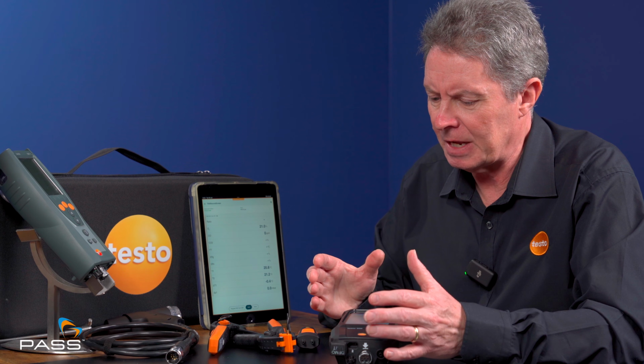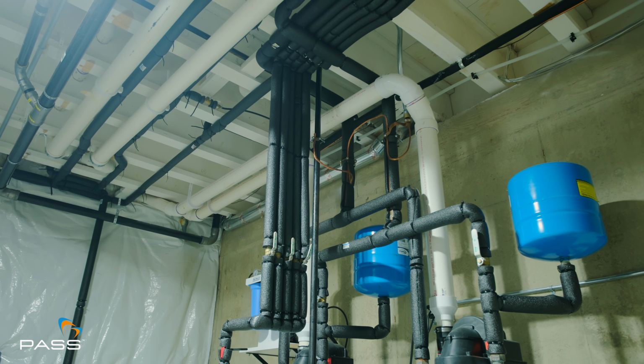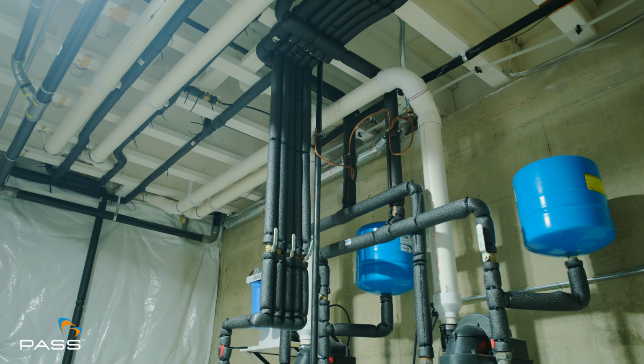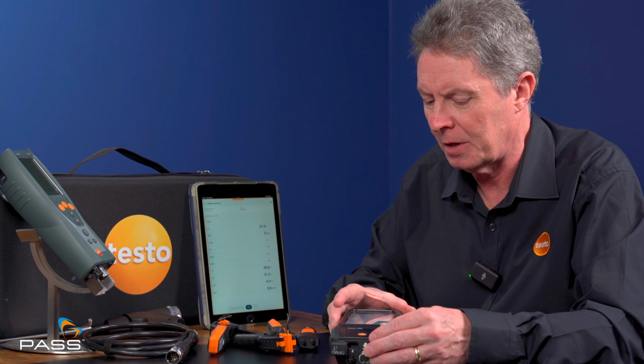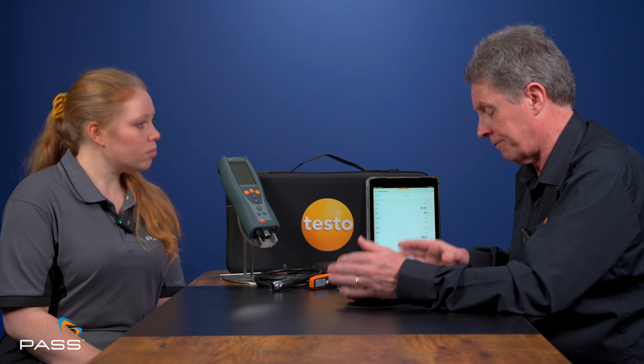And can we just quickly clarify what you mean by commercial and domestic? Okay, if you think about the size of a boiler, whether it's a small wall-hung domestic or a very large commercial one, they have very different combustion effects, with much more CO out of a commercial boiler. So it's all about buying the right analyzer for the job. For many years, we've seen people run up very large bills on a flue gas analyzer because it's not only about the initial purchase. With that flue gas analyzer, you have to have it serviced annually.